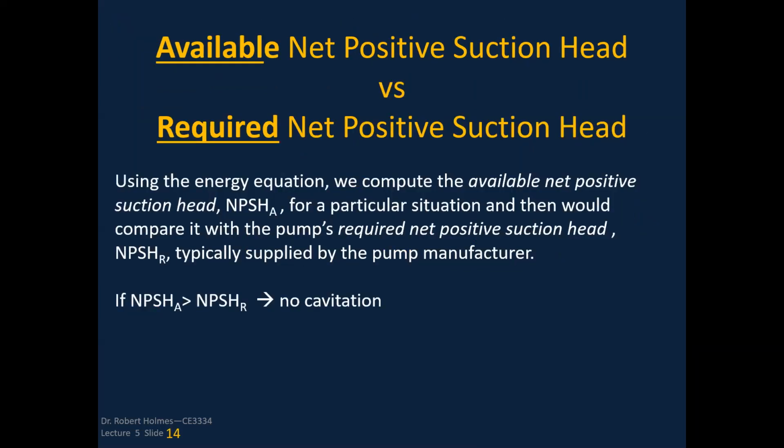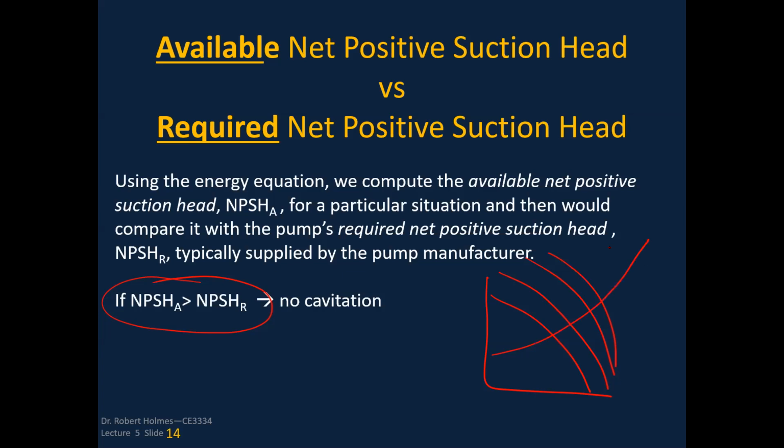And so what we want to do, as I've mentioned, is keep that net positive suction head available above the required value. When we design a pump, we've got this pump head characteristic curve. We haven't talked about it yet, but you're going to develop a system curve.